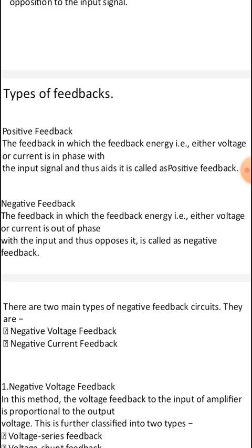So, the positive feedback increases the gain of the amplifier. It has disadvantages such as increasing distortions and instability. Normally we use the concept of feedback to decrease distortions, but positive feedback is increasing the distortions, and it is unstable. Because of these disadvantages, positive feedback is not recommended for amplifiers. If the positive feedback is sufficiently large, it leads to oscillations, by which oscillator circuits are formed.